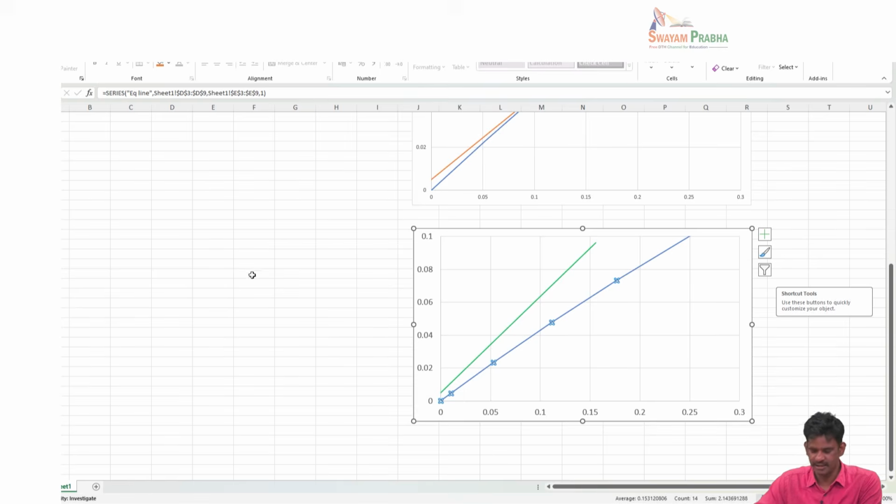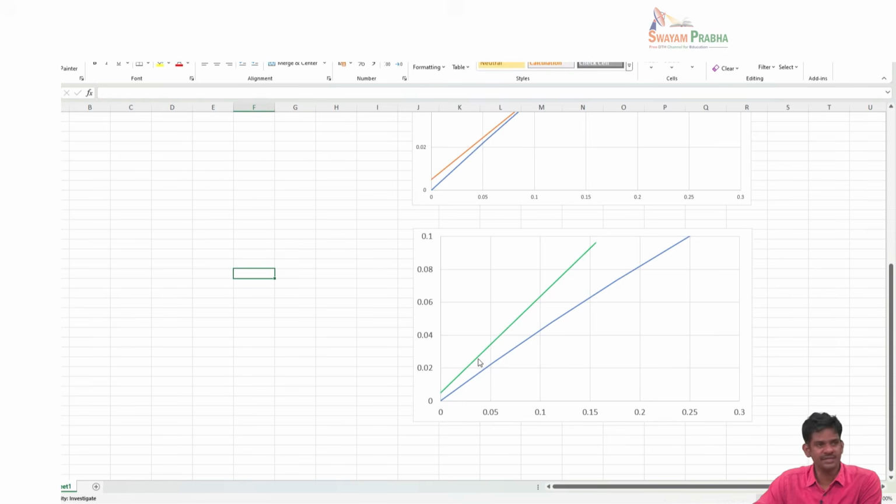Okay, so that's a blue line, and the operating line is shown as green here. Okay, so green one here, this point here is y1 and x naught. X naught is 0, so that's why this cuts at the y axis. Okay, so this will be like 0.005, and the other point here is based on the operating line, LS by GS value of 0.585. So y axis somewhere here is something like 0.074 or something like that, and here this will be 0.111. So the two ends are known.